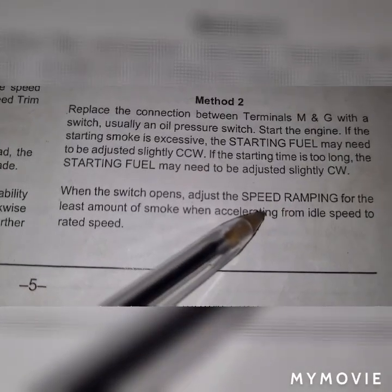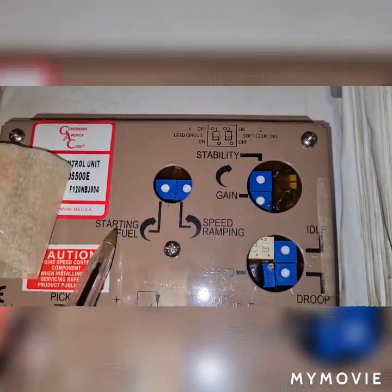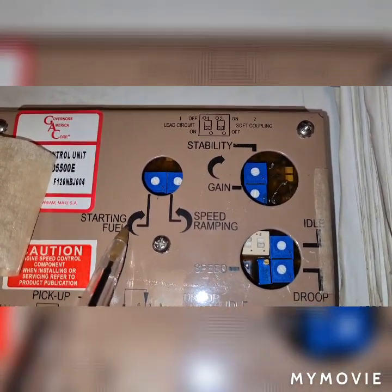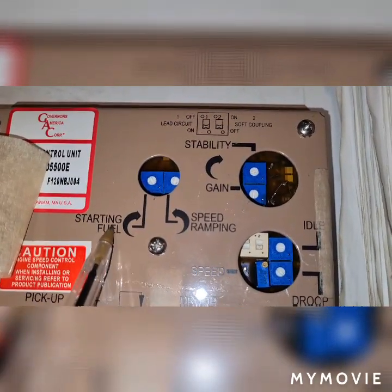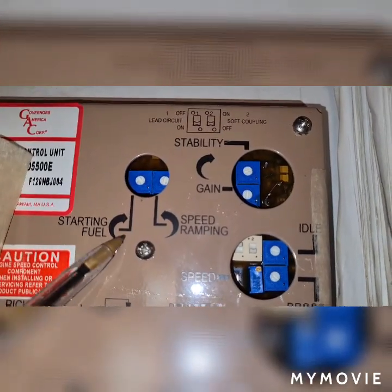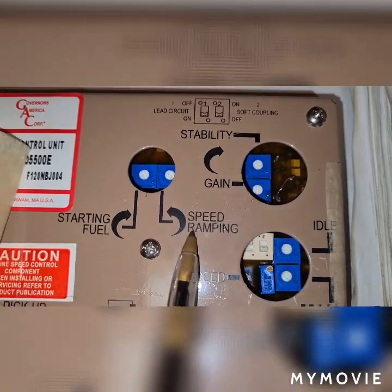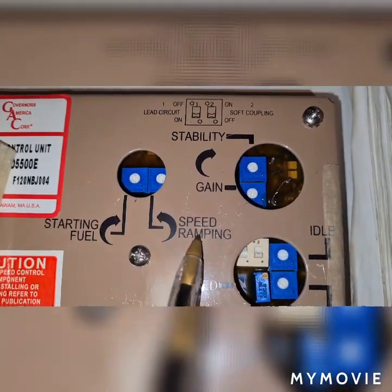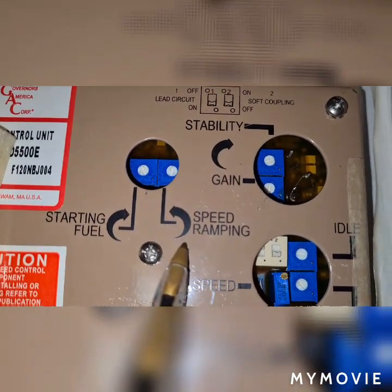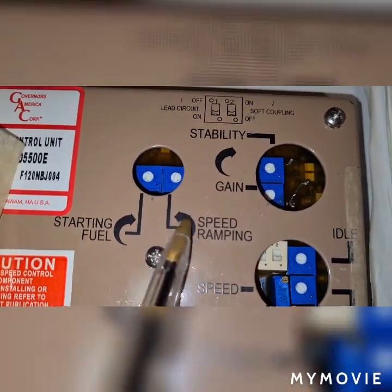So we have speed ramping here. So this is our speed ramping. Starting fuel, you can reduce the smoke emission while the engine is started, and if the rated RPM takes a long time to obtain, you need to increase the starting fuel. Then it is followed by speed ramping, which is the proper speed ramp time of your generator. Counterclockwise rotation shortens the speed ramping activity during starting mode.